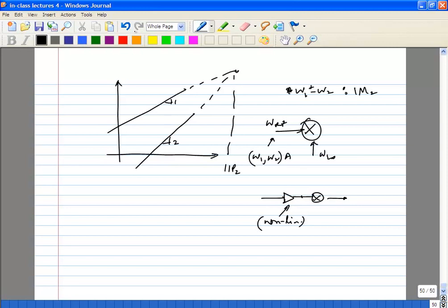And what you will see is, since you are all designing differential circuits, ideally your IIP2 will be infinite, because you don't have any even order components. So at the end of the day your IIP2 will be limited by your mismatch. That's why I said in the project assume a 1% mismatch, right? So the IIP3 numbers we saw were like minus 5 dBm and plus 5 dBm, right? Whereas IIP2 numbers will be plus 40 dBm or plus 50 dBm, something like that.